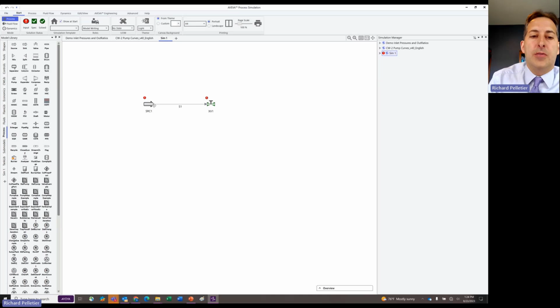It's connecting the information that's coming out of this model, connection point here, to the information that's coming in the inlet of this model here, right? So it's just a data transfer of what's being populated at that point that's coming out of the model and moving it over to here. Now, what's actually in the stream is kind of minimal. Or the connection, what's in the connection is actually kind of minimal, because all it's transferring is the minimum amount of information needed for the next model to be able to solve, right?